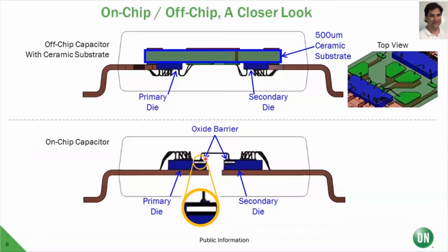With the on-chip solution, the capacitors are formed within the semiconductor silicon process using a thick SiO2, or silicon oxide, process. And this is, again, about 10 micrometers thick on each die, and they typically have two capacitors in series. So one of the challenges is if you have an electrical overstress event, you have to be careful not to exceed the power ratings of the IC, because if you get some EOS damage or carbonization on the die surface or within the die, it could impact these isolation structures and degrade the isolation performance. And we have a video that will show that shortly.